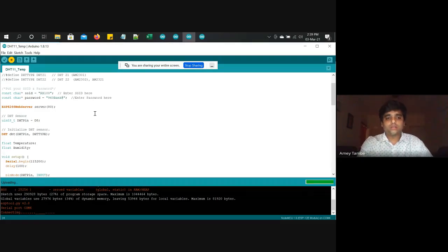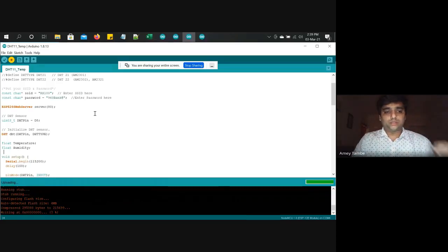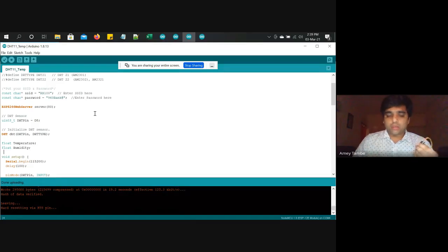Okay, I have connections on it, so that's why it is not getting connected. And yes, another troubleshooting would be if you are using a breadboard like this, and these are solderless breadboards, so it is having a continuous power flow. If I'm putting my NodeMCU with the power, it is automatically taking all the leads to the power, or I can use a breadboard extra power supply.